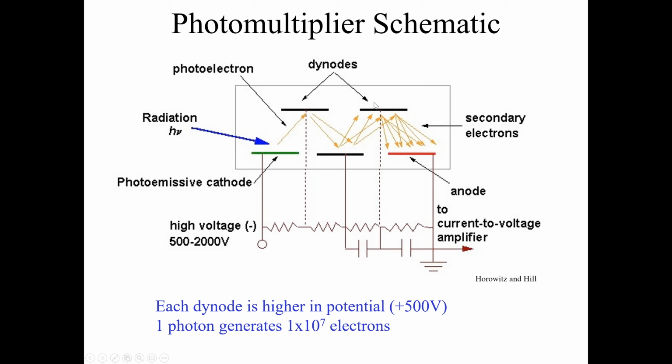It is so sensitive that if I were to take this part out of the instrument, just radiation from space enters the instrument chamber and causes a current to flow, and you'll see some noise. And even if I put this thing in a totally dark room, there is some dark current noise. So there always is some signal being generated in here. These multiplier tubes are not expensive. When we get into the Gen 4 and some of the newer stuff, it can get quite pricey.